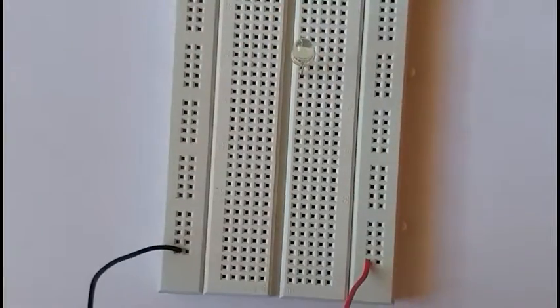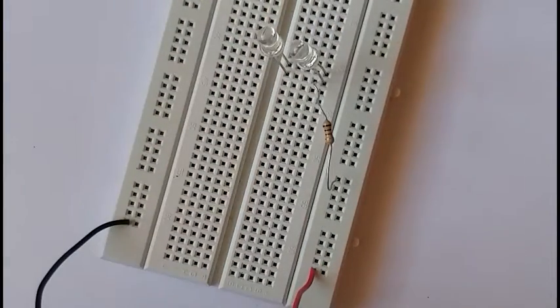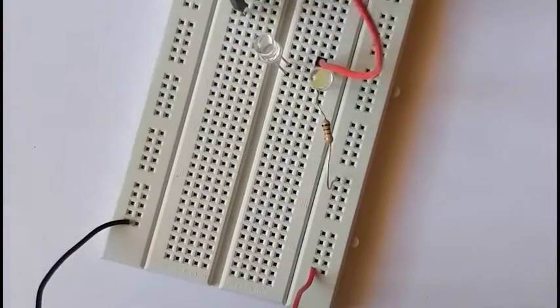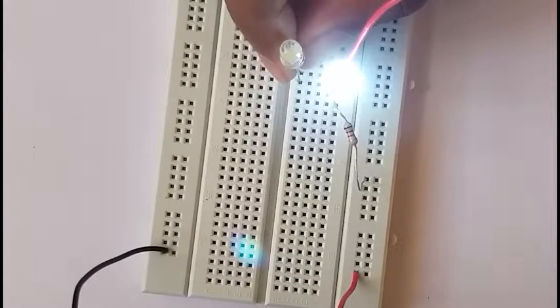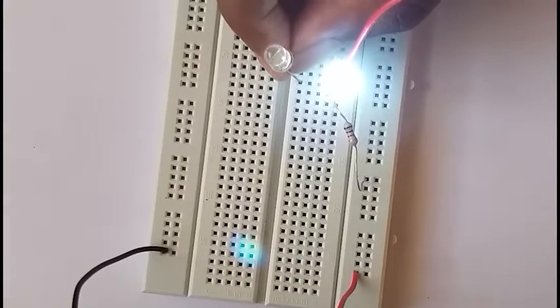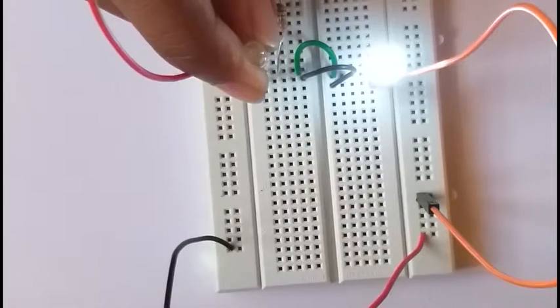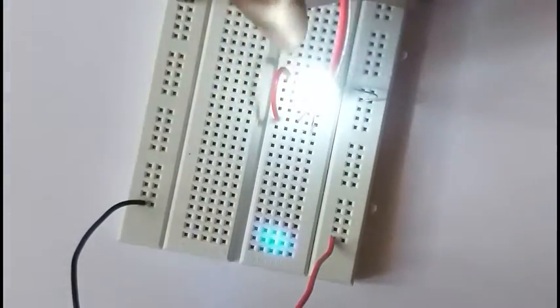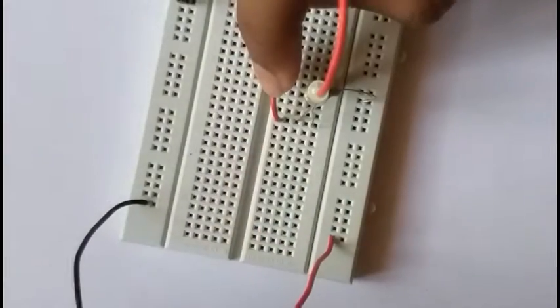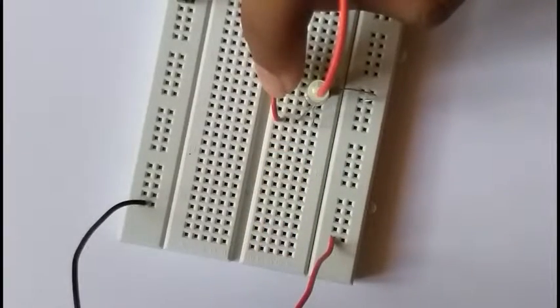For parallel configuration, connect the two ends parallel to each other. For LEDs' forward biased operation, connect both positive ends of the LEDs to the positive of the battery, and negative to negative. If one LED is removed, we can see that the other one increases its brightness as more current flows. When a wire is connected parallel to the LED, no current flows through the LED. Since the wire has the least resistance, the current chooses the wire's path.